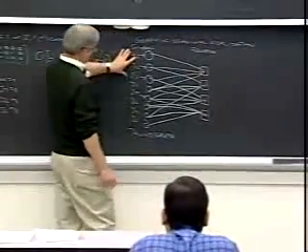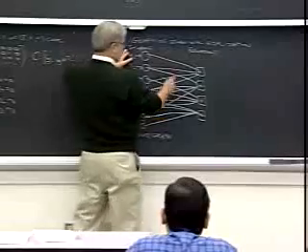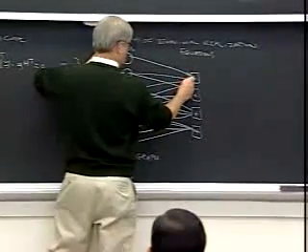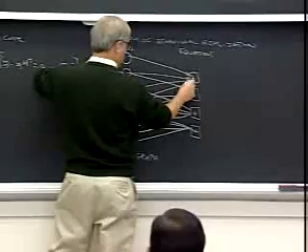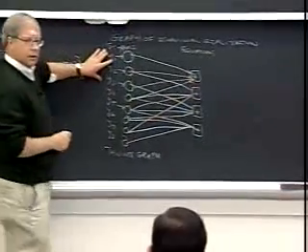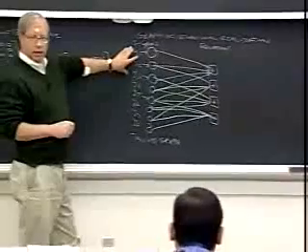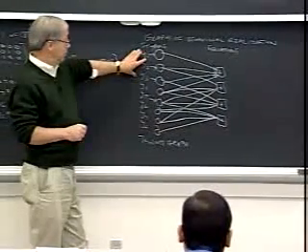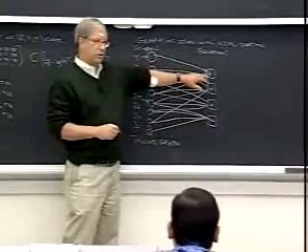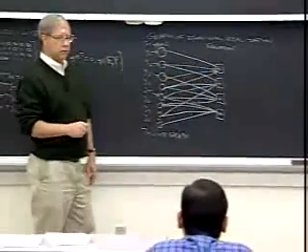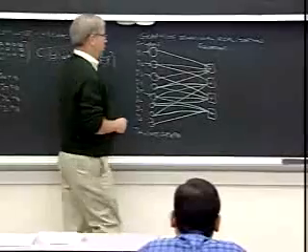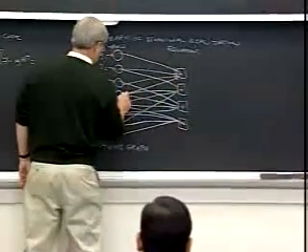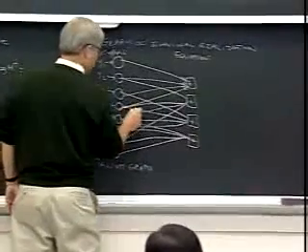These 3 bits going into this zero sum, these all go in. That determines this output, right? Any d minus 1 inputs, if d is the degree of the zero sum node, determine the last output, because the parity check has to check. So that determines this one, which then determines y4.